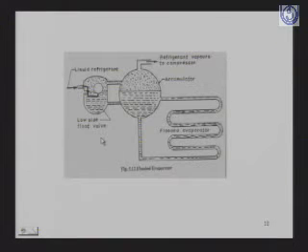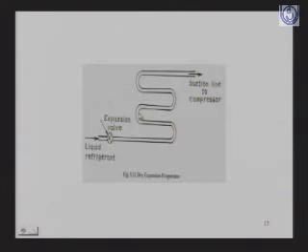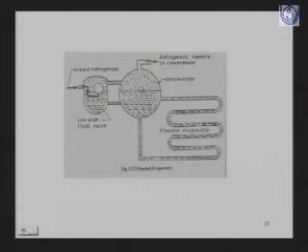evaporator. And if you see the flooded type, the refrigerant present is in liquid form. So this is the float, and this is the refrigerant. So it is the flooded type. Normally when the capacity is less, we use the dry expansion evaporator, and when the capacity is more, we use a flooded type of evaporator.